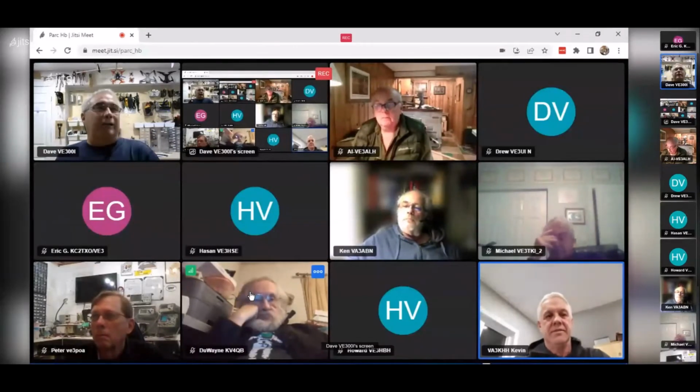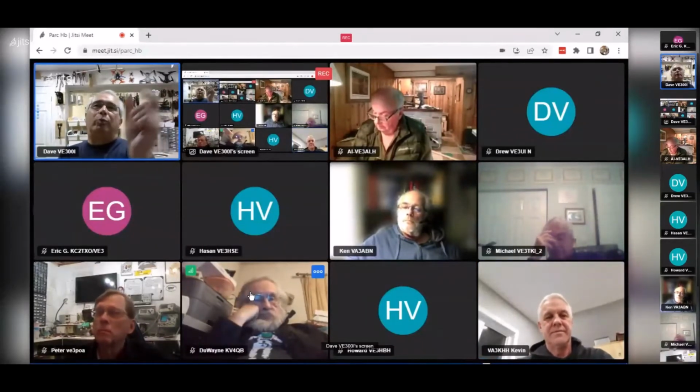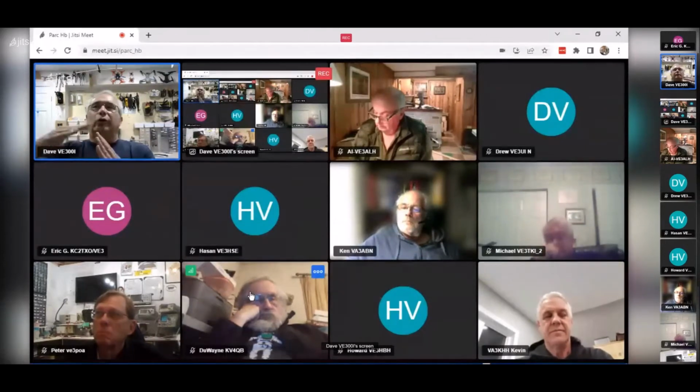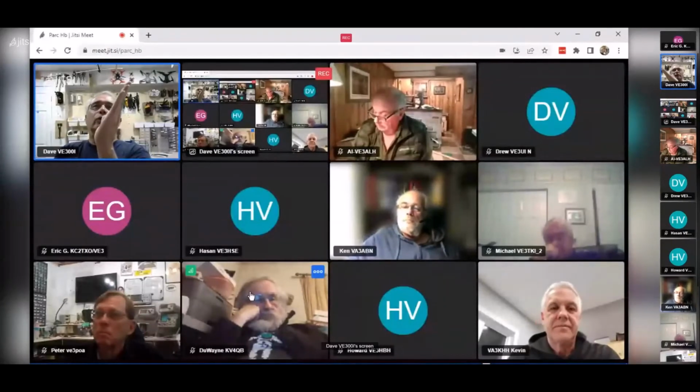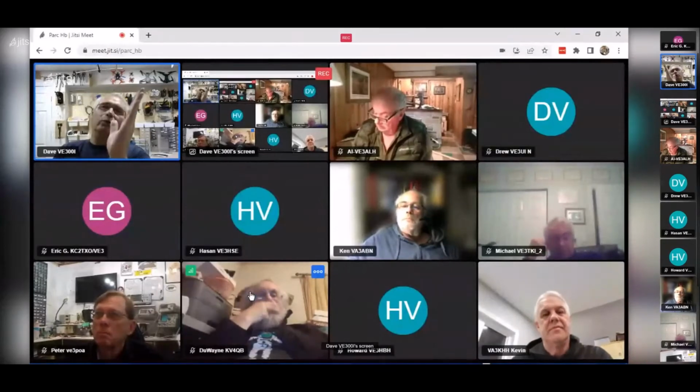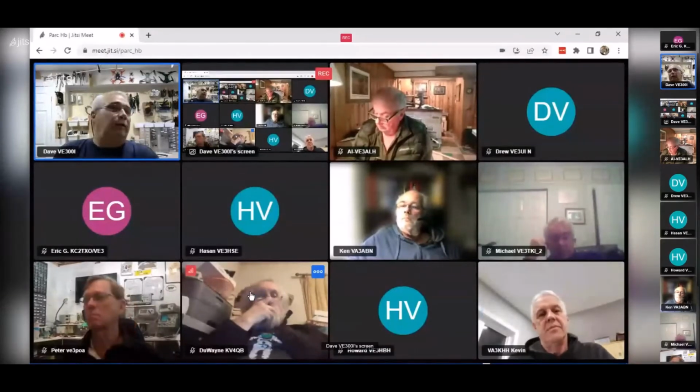Exactly right, and that's where I had that set point. To drive forward, I want my set point to be plus 10 degrees. So it would measure 10 degrees and hold 10 degrees. If it goes more than 10 degrees, it would come back, and if it goes less, it would go forward. No, so you're 100% right.